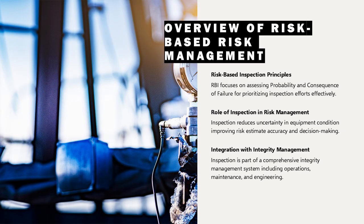Risk management with inspection activities is a structured approach used to ensure the safe, reliable, and cost-effective operation of pressure equipment and industrial assets. This approach is commonly aligned with risk-based inspection, RBI, principles, where decisions are driven by an understanding of both the probability of failure, POF, and the consequence of failure, COF.